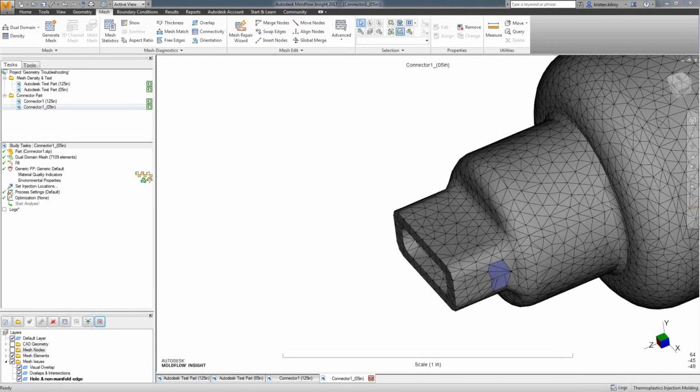Granted, it's not going to be significant unless you have a lot of round features on it, but it's just something to take into consideration whenever you're looking at it. And if you're really not happy with that, then you can also go to 3D mesh. If you're working with thick, chunky parts, or a lot of round features, then sometimes 3D mesh might be able to better capture it just because you're really seeing that internal mesh.